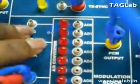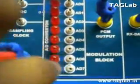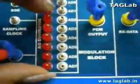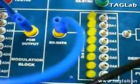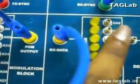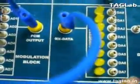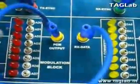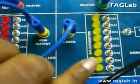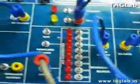Here the signal has been converted from analog to digital. You could see AD0, AD1, AD2, AD3, 4, 5, 6, 7 up to AD7. The 8-bit data has been shown over here. In a similar way, for the demodulation, you could see the signals DA0, DA1, DA3 up to DA7 also obtained on the board itself. Thus, you could see the ADC output as well as the DAC output in the pulse code modulation demodulation trainer kit.